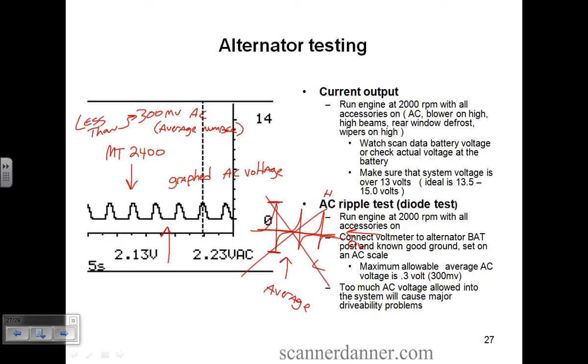All right, but here's the symptoms with this vehicle. Transmission would go into limp mode. And when it would do it, the vehicle would violently shake, like to a point where, you know, if you had false teeth, it'd shake the false teeth out of your mouth. That was how bad this vehicle would shake while I was driving it. I don't remember why I suspected the alternator right away. I believe whenever it would act up, the gauges would go all over the place on the dash. And what I did initially, before I did this measurement, I just disconnected the alternator.